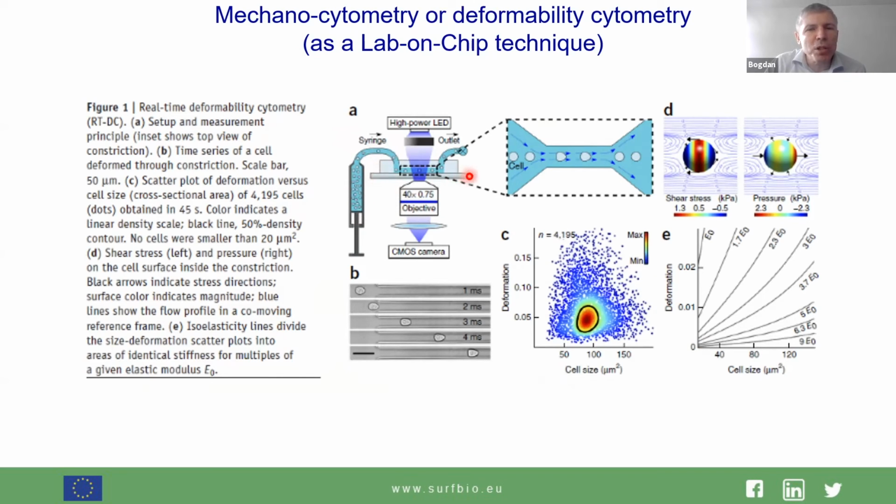So this is a side view. This is a glass. We see here this material that makes microfluidic devices. This is PDMS, low temperature transparent material. And then view from the top, we can see here that there are some areas where cells are not pressed on, and there are these areas in the middle, constrictions, and we can see microscopy. Everything is easy in regard with microscopy. These are the transmission microscopy images. When we look here at cell deformation and deviation from circularity.